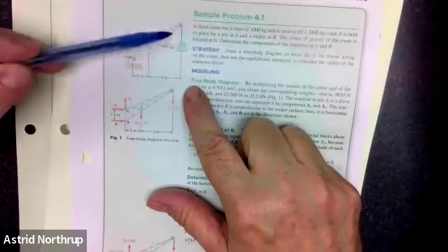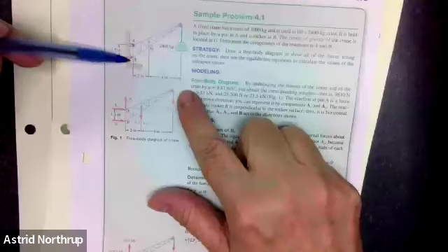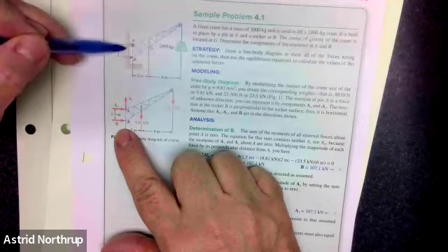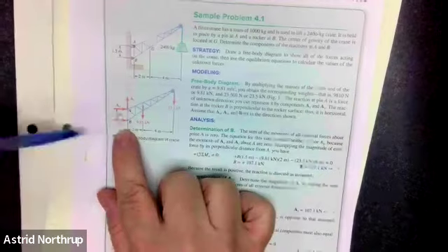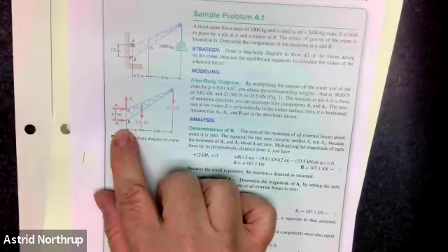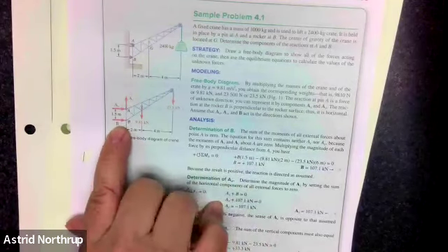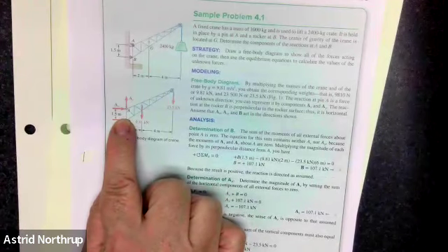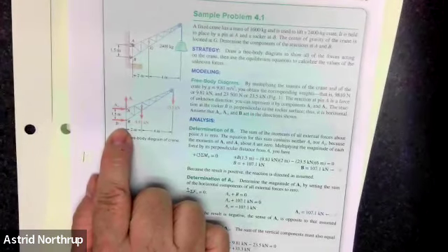We have this kind of a crane bearing a weight anchored into the wall. Now, the way that this is drawn, A is a pin, which will bear an X and a Y force. B will only bear an X directional force because it shows it as a non-fixed support. So those are the first things that you need to draw. The other thing I would strongly suggest to you, like if you think about the reaction force at B, you know that B is going to be pushing out on this crane.